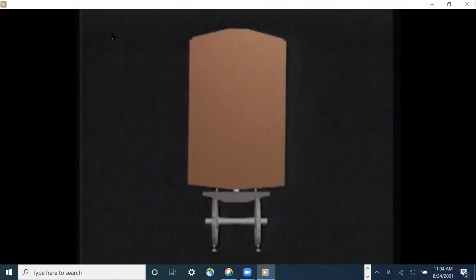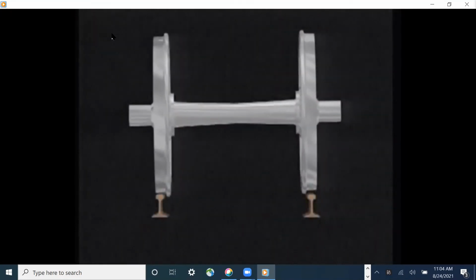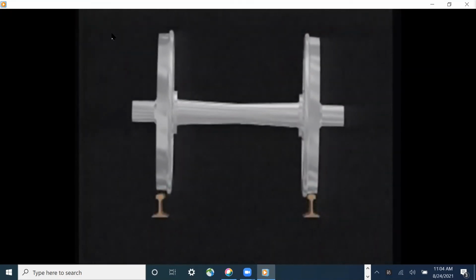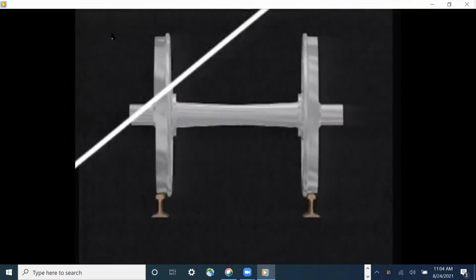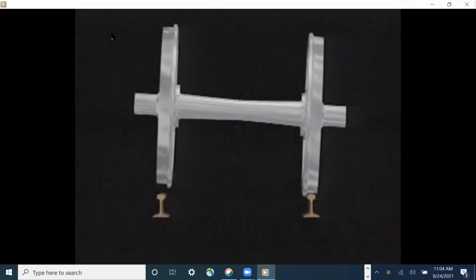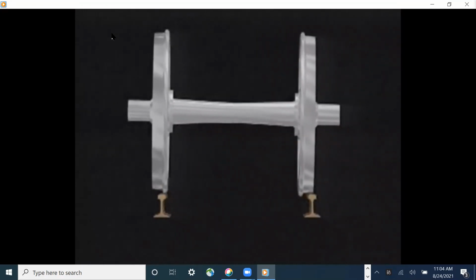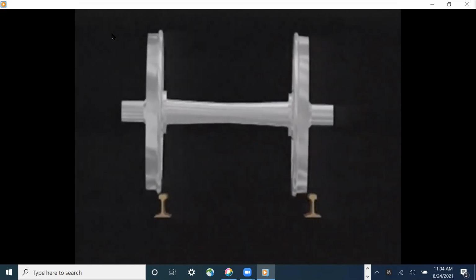This rocking magnifies the alternating vertical load on each rail, causing wheel unloading and possibly wheel lift. If this occurs on a curve, the wheel may come back down with the flange on top or to the outside of the rail.